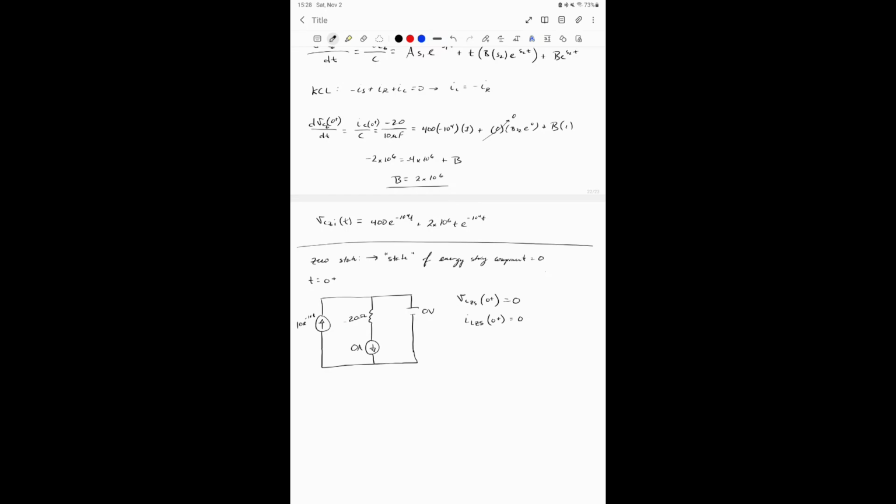And we basically have all of this current going down here, right? Because I mentioned in the last video, if this is 0 volts, that means nothing's dropping, but you can still have a current. This is 0 amps, so no current is going down here. So this is going to act like a short circuit. All the current is going to go down this way. So IC is actually equal to IS. And it is still going in the correct direction, so your IC is equal to your IS.